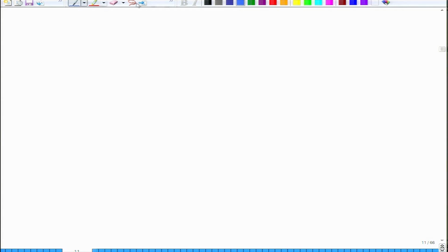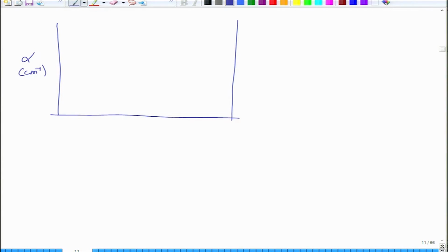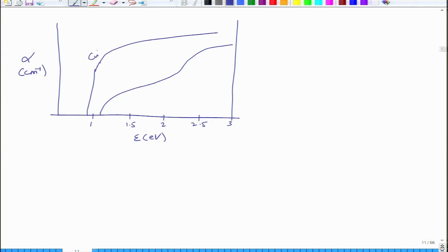The genesis lies in the difference in the absorption coefficients. So if you draw, for example, absorption coefficients of different materials, silicon has a band gap of 1.1 electron volt. So let's say we plot it from 1.5 to 2.53. This is E in eV. Okay. So silicon has a band gap which is lower, and hence it will start at somewhere here. Okay, and this goes a little bit lower band gap, which increases somewhere around here. Okay, and then we have copper indium gallium selenide, which is an even lower band gap, but its absorption coefficient is actually pretty good. So this is CuInSe2.